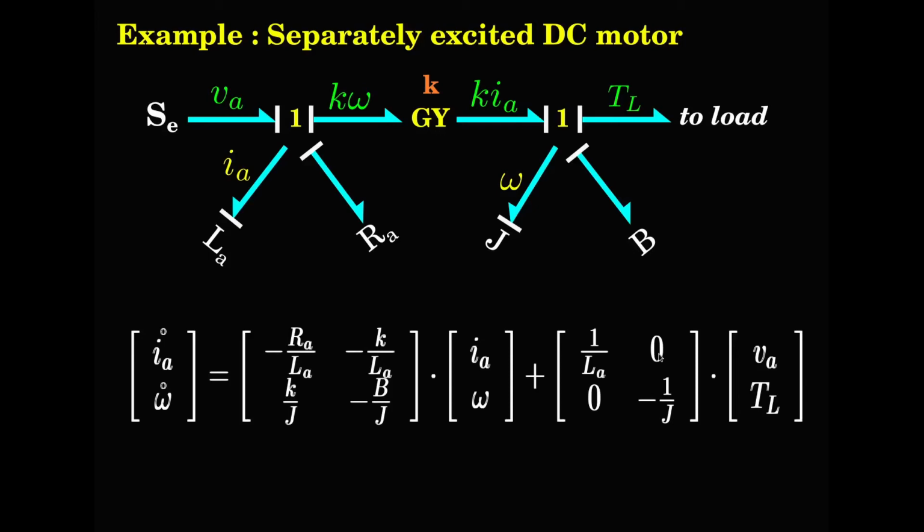So we will use that to design a controller. We'll use this plant model definition to design a controller using the root locus method. VA is the armature voltage, which is an input. TL is a torque input, and load torque is not known, so it is considered as a disturbance input. So as far as the control input is concerned, it will come through this VA variable.